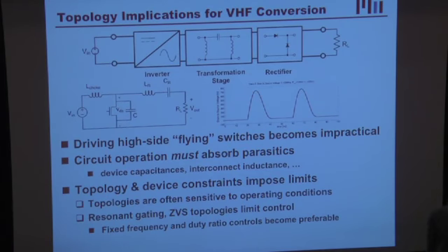What do I mean by that? In conventional design, what you might do is think of your semiconductor switches as ideal switches, design your circuit, and then the circuit parasitic capacitances or the package inductances are some second order term which I try to manage or ignore, but they're not baked in as part of the process. There's just a secondary loss mechanism. When you get to sufficiently high frequencies, you can no longer do that because these parasitic components become a substantial fraction of your overall circuit.